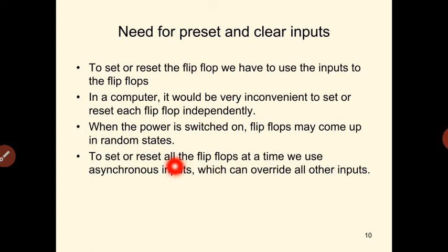To set or reset all the flip-flops at a time, we use asynchronous inputs, which are called preset and clear inputs. Preset and clear inputs are called asynchronous inputs, which can override all the inputs. So that is the main advantage of using preset and clear asynchronous inputs. That is the need of preset and clear inputs.